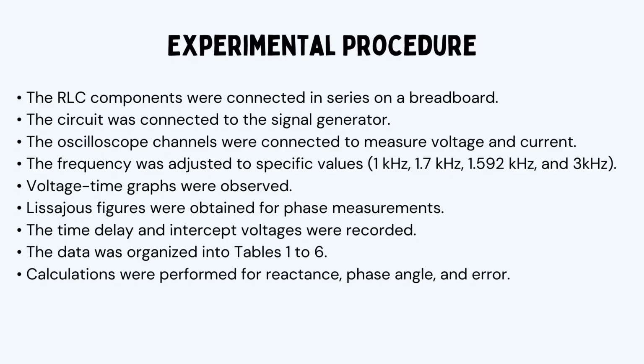For each frequency, I observed the voltage versus time waveforms. Then I used Lissajous figures to measure the phase relationship. I recorded time delay and intercept values as needed, organized everything into Tables 1 through 6, and performed calculations for reactance, phase angle, resonance frequency, and percent error. Now I will show my recorded results for each frequency.